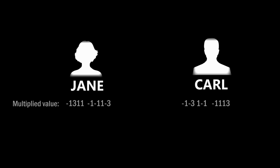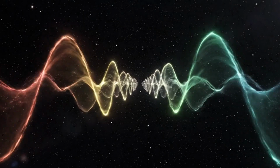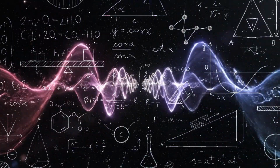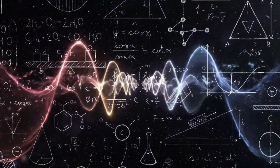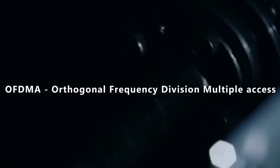Repeat the process for Jane and Carl's spread code. The answer received should match Ben, Jane and Carl's first assigned value, and hence it is decoded. This is how we can triple the use of one channel with assigning a spread code and using some math. But this happens in a large scale. With the explosion of smartphones and the need for streaming data, engineers developed a new method called OFDMA.